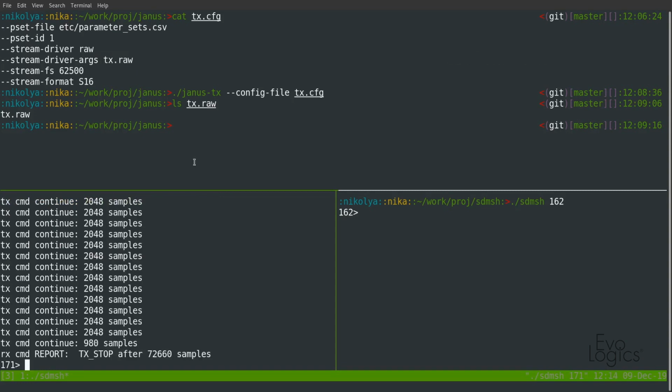Great. Now let us talk about JANOS reception. The duration of the JANOS preamble is slightly longer than our standard reference signal, length of 1024 samples. Therefore, it is not possible to use our standard signal detector to receive JANOS signals. We implemented detection of JANOS preamble on the SDM modem level. Signal detection is performed on our low modem hardware level. Once a JANOS preamble is detected, the modem estimates the Doppler shift and the first symbol's reception offset. These parameters are transferred to our modified JANOS RX that skips signal detection and begins with demodulation straight away.